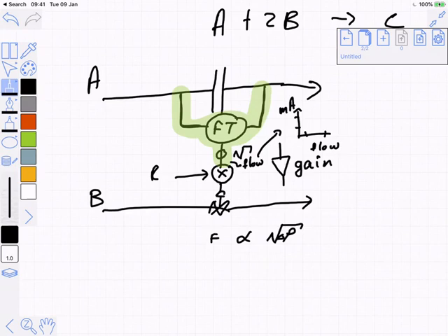That's the mechanics, right? The mechanics are, at the minimum, I need some kind of piece of machinery that measures one of the flows. And at the minimum, I need some piece of machinery that manipulates the other flow. Something that is also not always 100% clear to people is why this is feed-forward control.